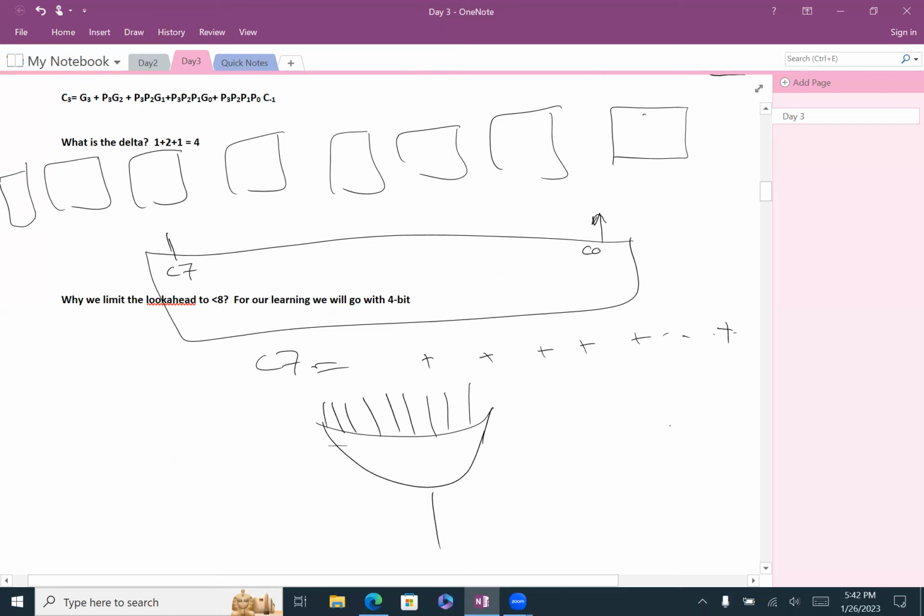And what we said about this design, we're not supposed to use a gate with more than 5 input or 4 input. Let's assume 5 because we did 2. So in this case, can we use an 8-bit carry look ahead? No, we cannot use it. So in this case, what can we do to solve this problem?